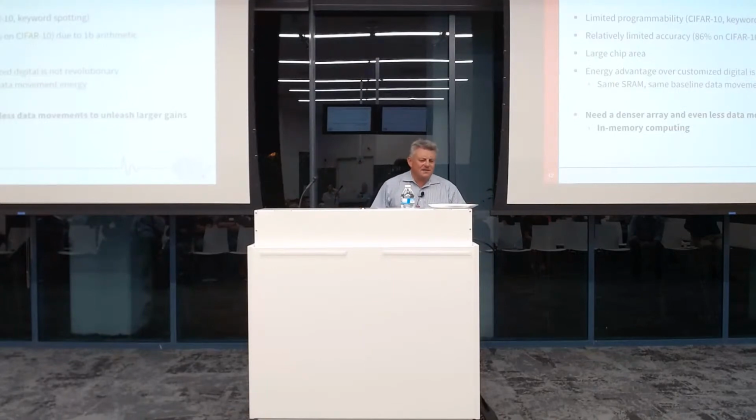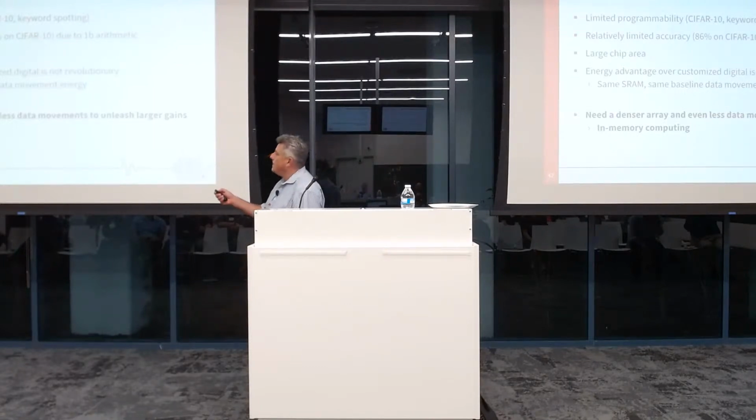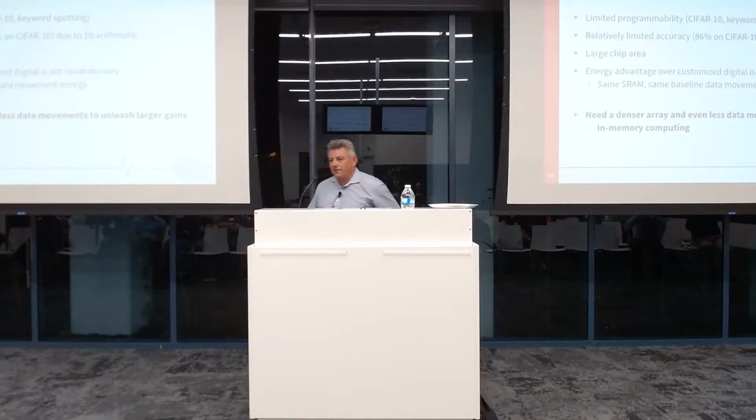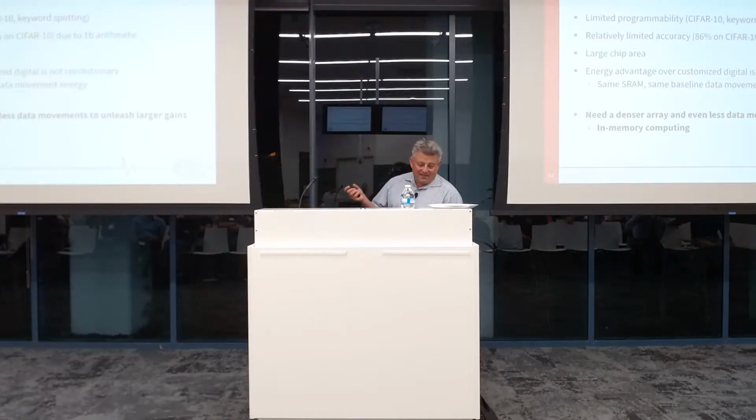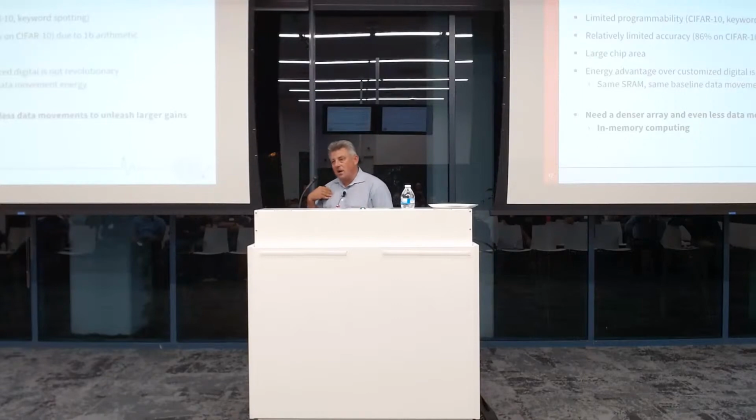Well, first of all, this thing is not programmable. I mean, everyone who knows software here knows that this thing is not going to fly in a product potentially. You could do CIFAR-10 with it. We also did keyword spotting. It works reasonably well if you give the spectrograms as the input. But the accuracy was no good because we run 1 bit. It's actually not so much the 1 bit, it's more the 2x2 filters that cost us more performance. And then the chip is large. And lastly, and this is the nail in the coffin, the energy advantage over hand optimized digital is not revolutionary. So if I was doing a company, and I have this thing and I consider time to market, I'm going to go digital.